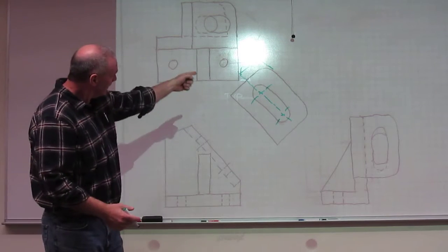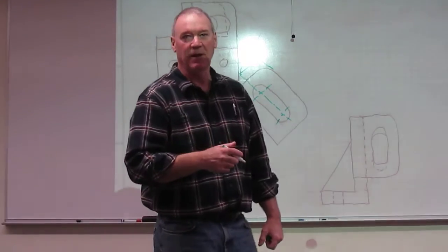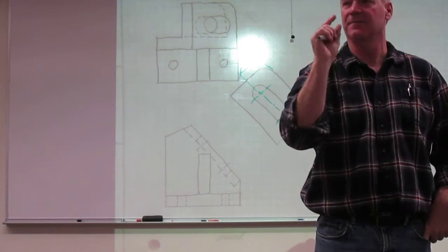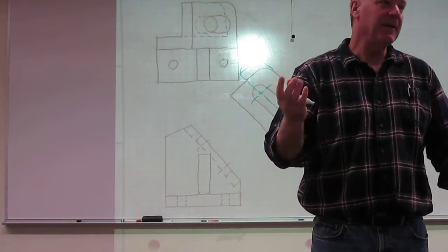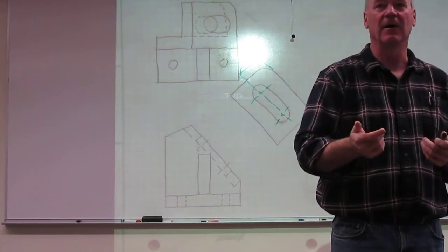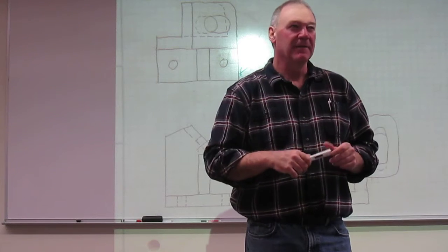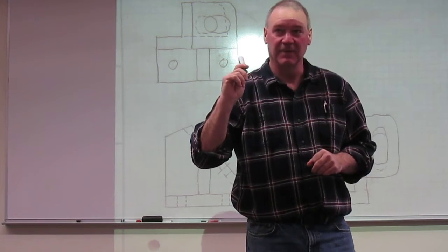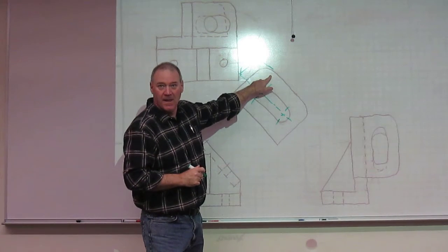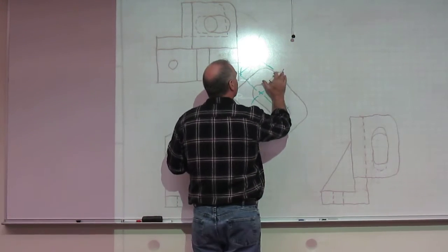Now, in essence, you can't see it on a computer screen unless you're using the line weight display option. Some of you use that, right? Where it estimates the line weight and shows you these real thick lines versus thin lines. Most people don't, I don't, because for me it clutters my screen up and I can't see my snaps as well. But when you print it, you've got to remember that this is a fairly thick line, right? You're looking at it on the computer screen and there's a gap right there, and then you print it and the thing looks like this.